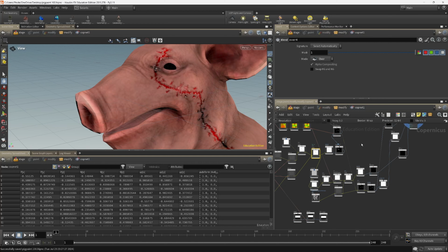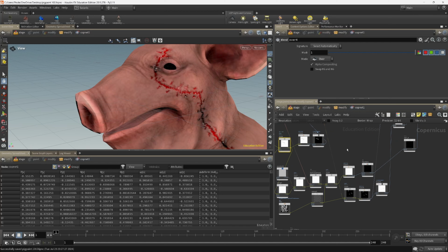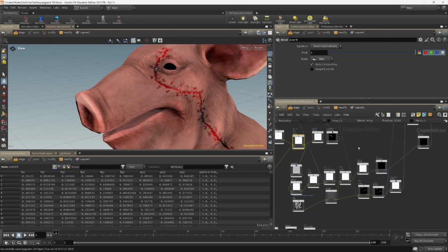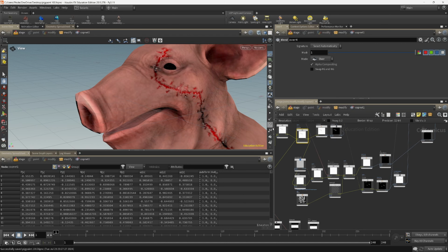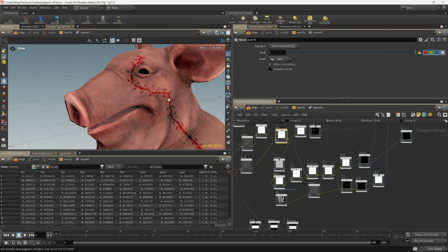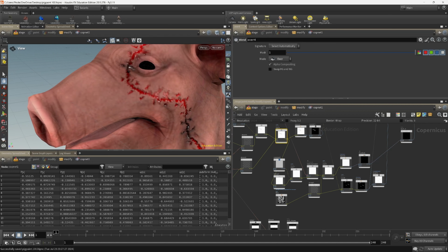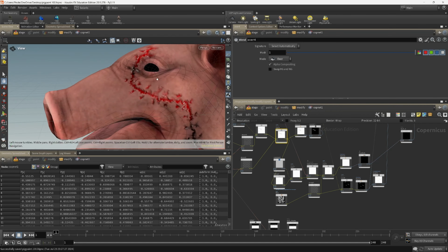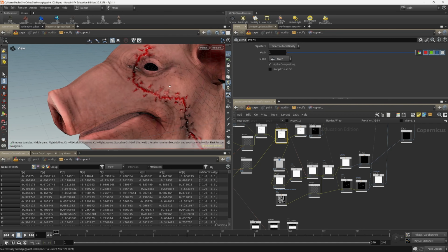All right, just to save on time, because the point of this was to do an R&D into different ways to rasterize from world space to UV space with stamping and restoration of geometry and orientations, etc. So I've just gone and added this, and I'll explain what I've done. You can see now that there's a height map. One thing that's kind of helpful is to put your view into wire, and you can see what's negative and what's positive relative to the map, which is kind of useful.